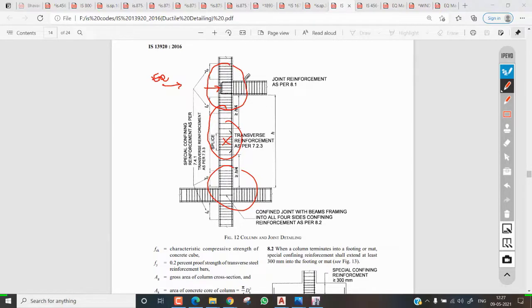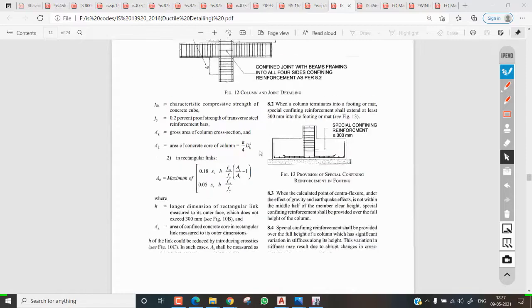At that time, these joints may deflect, or some stresses will be induced. So that's why we increase the shear reinforcement. If it is an earthquake, it is shear reinforcement, right? If you want to resist this shear, we need to provide ties, shear ties, stirrups. So that's why we increase the stirrups exactly wherever we have junctions. Earthquake and wind load mainly act on the junctions. So that's the main reason why we provide this type of arrangement.